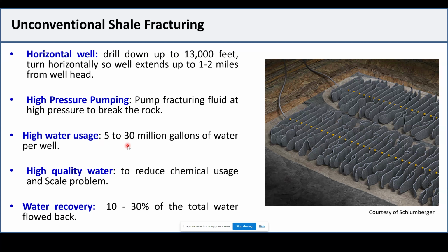If you are looking at current technology in frac fluid, it is how we can use the produced water. A lot of companies have succeeded, including BP. When we have plenty of produced water, we tend to use it to try to reduce the water quality demand. The bad part is that whatever you inject there, you do not get back 100%. Usually you get 10 to 30% of whatever water you are injecting.